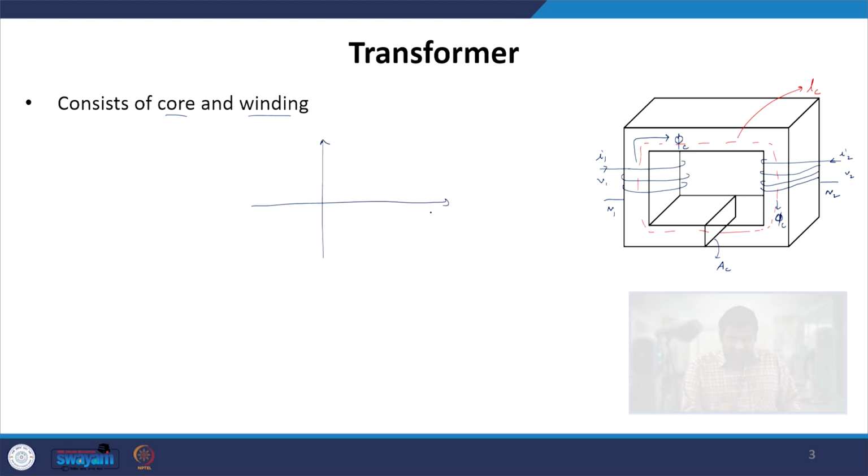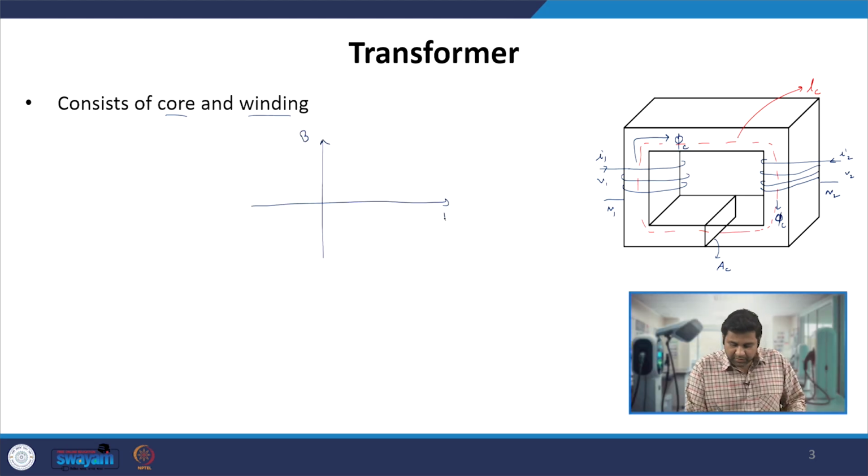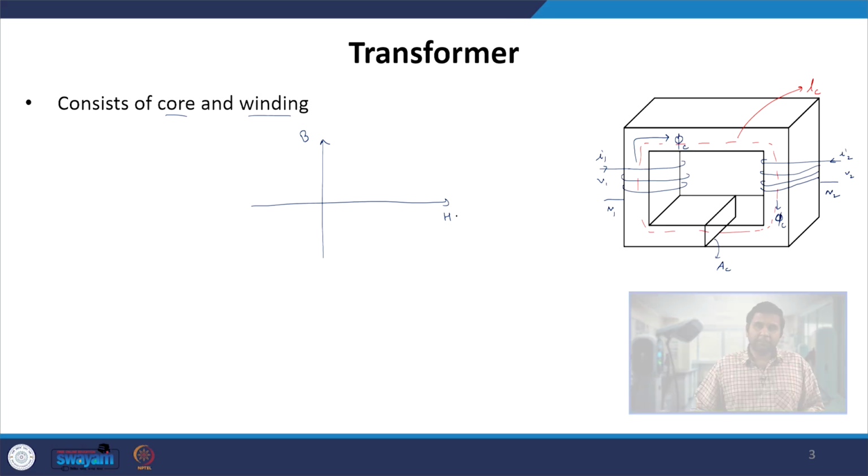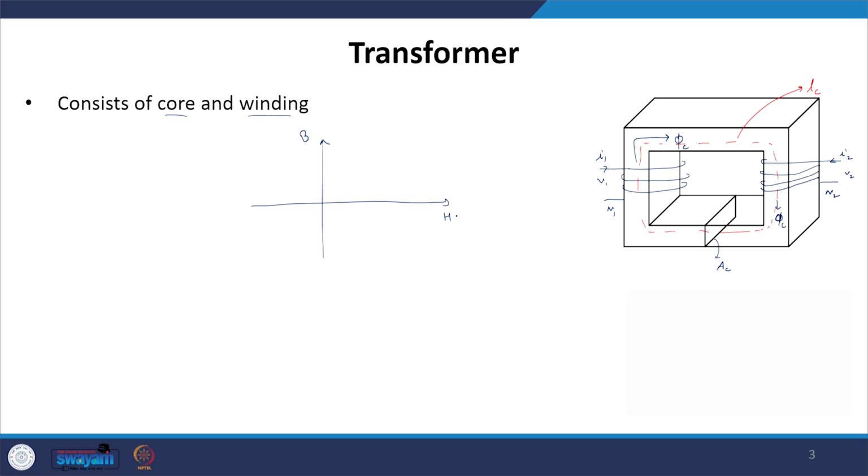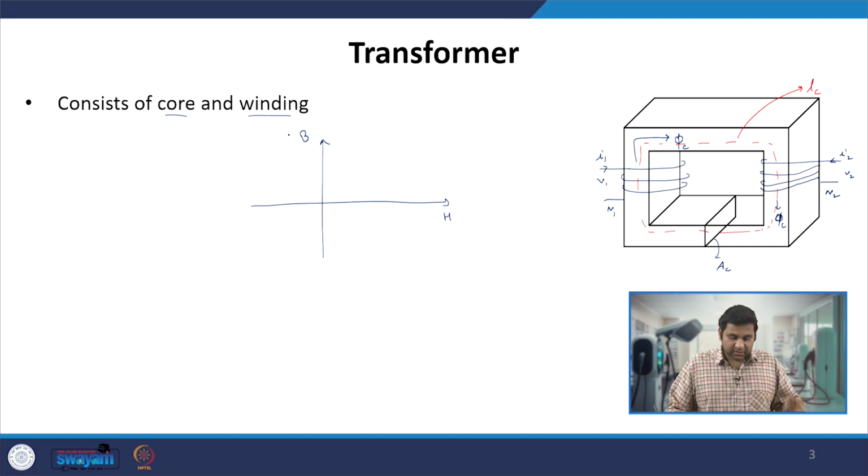So that is why it leads to a curve called the BH curve, where we have the external magnetic field applied onto the core material, and as a result there is a magnetization in the core, which leads to the generation of some net amount of flux, defined by the flux density term, which is called B. So this particular thing will have a shape something like this,